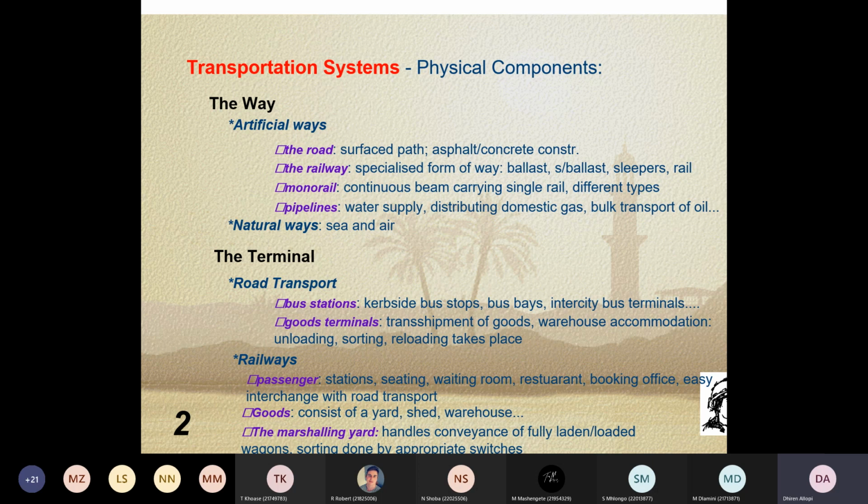With railway design also, similar to asphalt and concrete, similar to flexible and rigid, we have what we call a ballast system. Now, a ballast system is again similar to a flexible pavement design, where you have single-sized stones that are laid over your subgrade layer. So you have a sub-ballast, and then you have a ballast. The ballast being more superior to your sub-ballast in terms of the crushing value of your stone, in terms of other factors relating to strength.